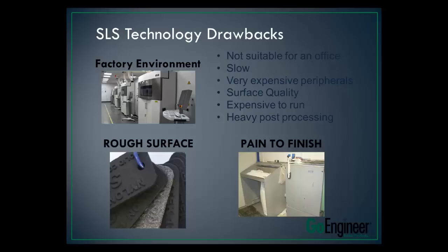You can run a part once a month, once every 2 months, once every 3 months, and be okay with it. Machines like this and the MultiJet machines rely on you running them almost constantly to keep the heads clean, the motors lubed, all this other stuff. If they sit for a long time, that might be an issue.